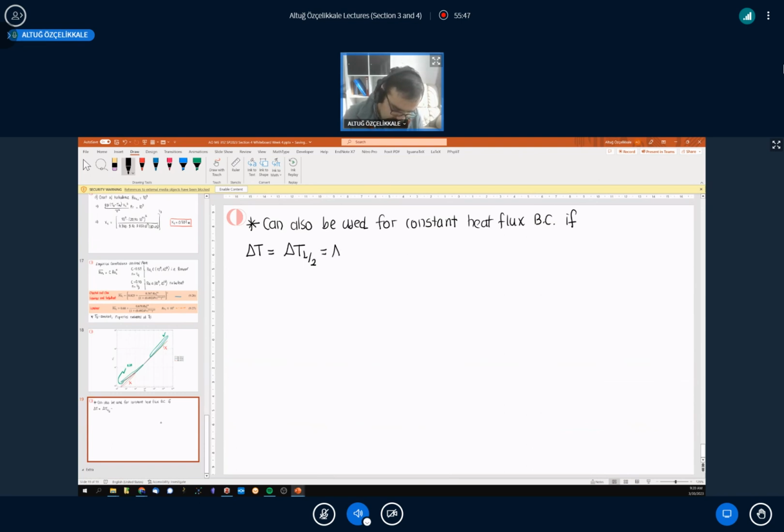That's equal to delta T, I'm sorry, that's equal to Ts at L/2 minus T infinity, or vice versa, is used for calculation of Rayleigh number and Grashof number as well. And also, we are using that in Newton's law of cooling.